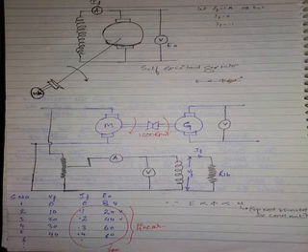This is the maximum voltage the shunt generator can build up. Let us say this is O, this is Q. The length of OQ in volts is the maximum voltage the shunt generator can build up. Make a note like this. The intersection of the field resistance line with OCC, in brackets point P,